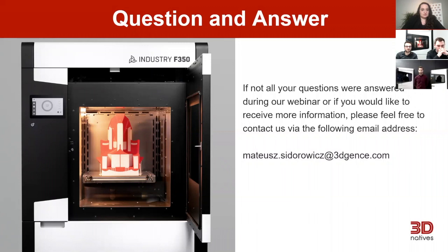Chemical resistance is sort of similar. There are some thermal differences. For instance, PEEK has a glass transition temperature of around 140 degrees, while PEKK is slightly more resistant at 156, I do believe. Well, again, depending on the grade. There are significant differences that can make or break an application, but a defining difference other than just chemistry and applications is hard to pinpoint, really.